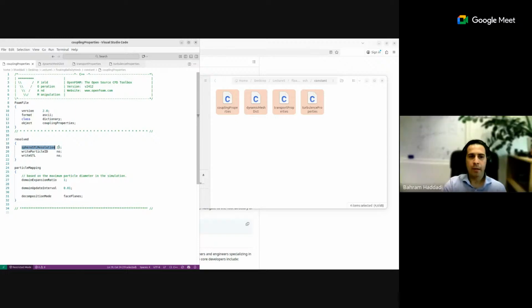Yes, that's right. Okay. Then on the CFD side, we convert them to STL, and this number defines the resolution of the STL. The bigger you make this number, the finer and consequently smoother the surface, but as a result, higher computational effort, because forces on more surfaces need to be calculated. So I recommend a decent value, around 20 or 30, and that should do the job. If you have a single sphere or a few spheres, go for a higher number. But if you have a few thousand, a few 10,000, you can stick to something between 10 and 20.